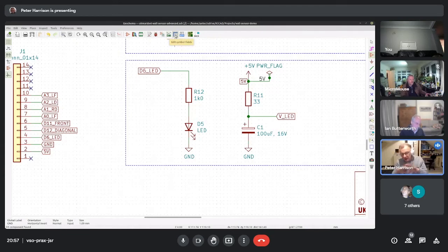you can make a kind of spreadsheet and go and edit all of the fields of the parts. So if you were designing for manufacture, so if I were doing UKMARS block from scratch in this, I would go through the symbol fields and I would add in things like supplier part numbers or those kinds of things.